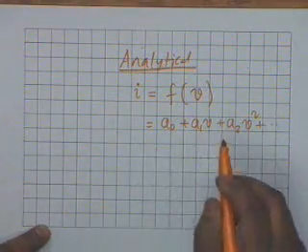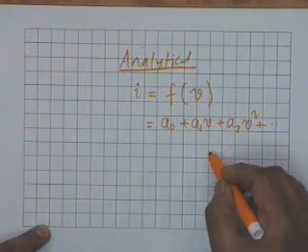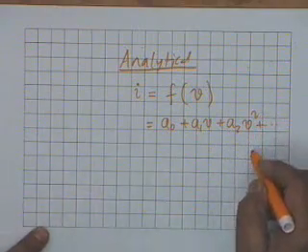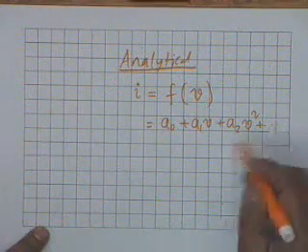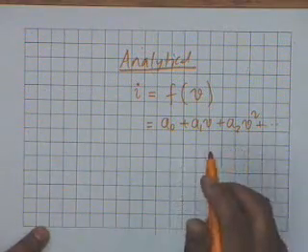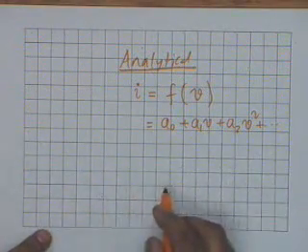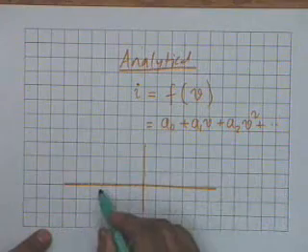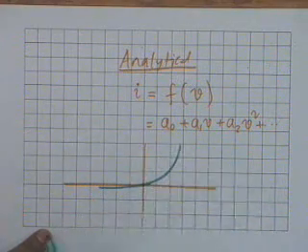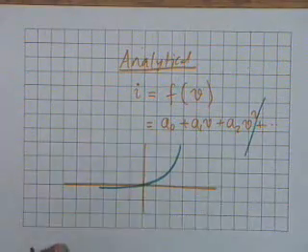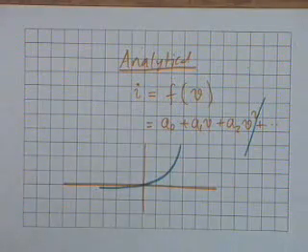If you stop at the second term, then obviously there is a linear approximation. If you stop at the third term, then it is a quadratic approximation. If you stop at the fourth term, cubic, and so on and so forth. So the more terms you accommodate, the better is the approximation. For example, consider the characteristic of a diode, and you want to approximate it up to the quadratic term, that is the squared term.